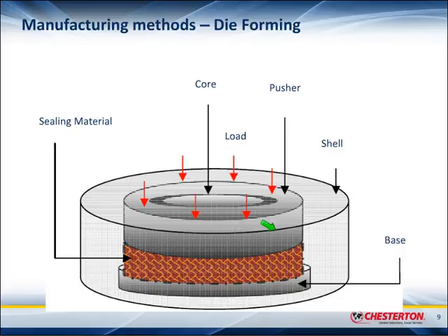It has a controlled density, and as well a controlled height. As I mentioned, this manufacturing method can be used to make flexible graphite rings, but it is used as well to make braided packing into die formed rings that have a more accurate size and a more controlled density.